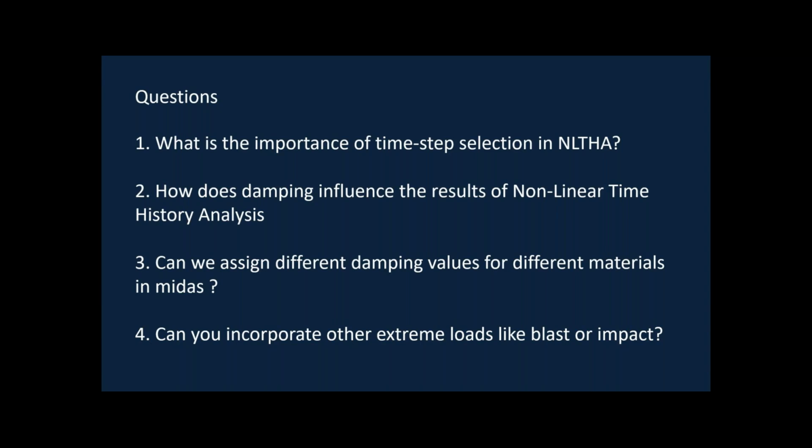We generally prefer the mass and stiffness proportional damping so that we can get a range of damping for different modes of the structure, so that the entire range of the structure is covered. So you can use that.